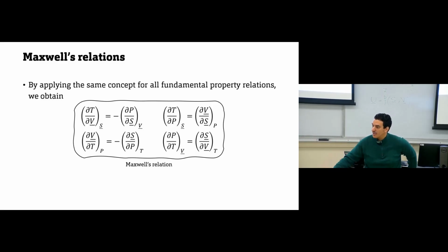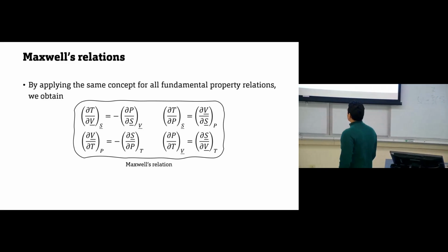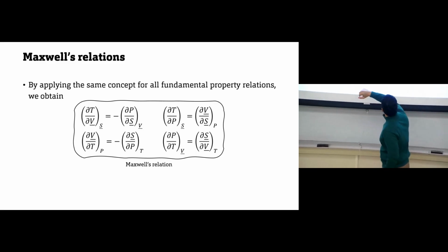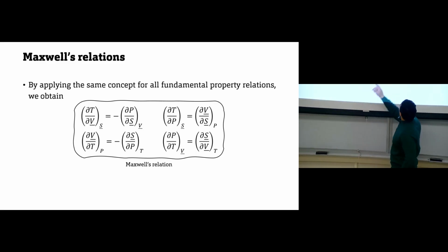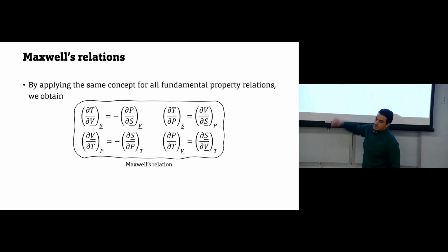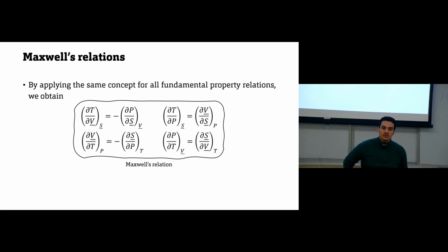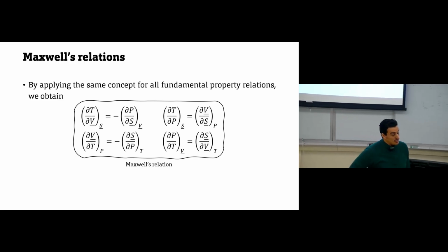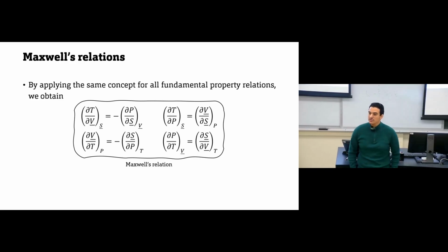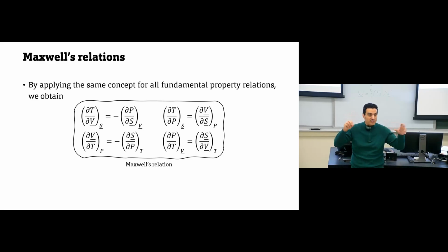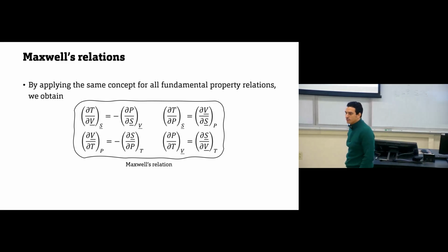I can tell you: use the ideal gas equation of state, use the Peng-Robinson equation of state, use the Soave equation of state in order to find the value of this partial derivative. But if you have any partial derivative that contains entropy, for example, or internal energy, or a property at constant entropy similar to this one, we cannot solve this partial derivative using the equation of state. So keep these things in your mind, because this is what you will see in the model, and this is how we are thinking while we are working on this model to develop the final form. Clear?